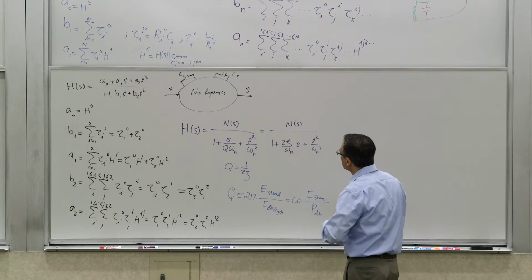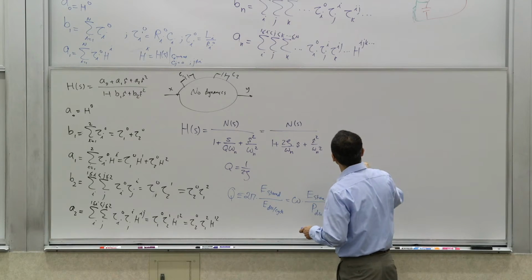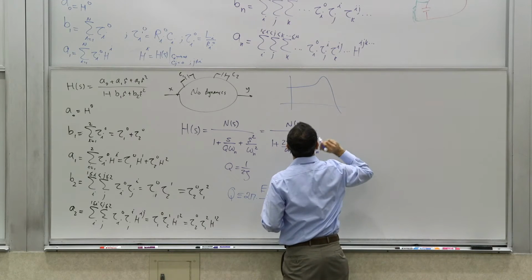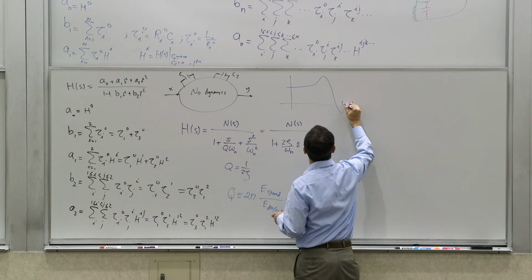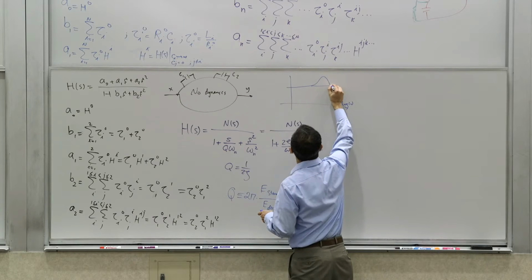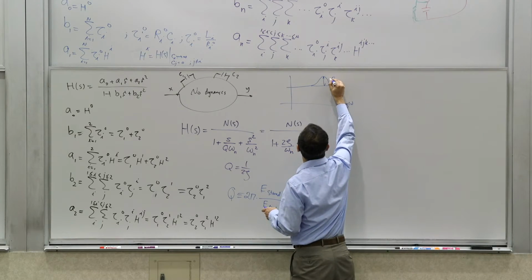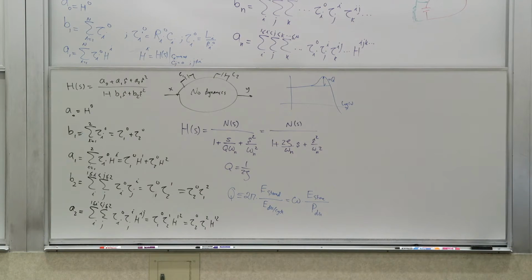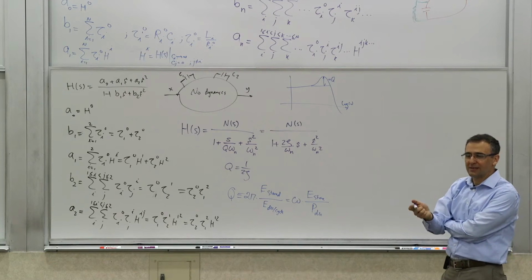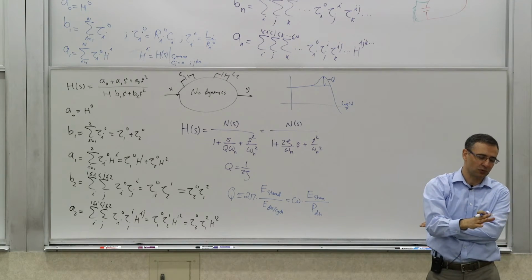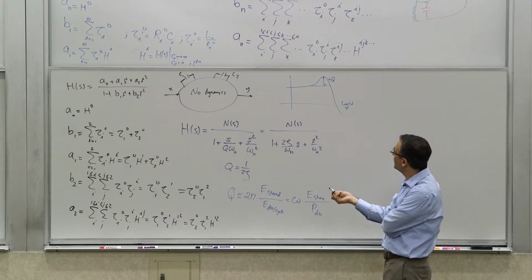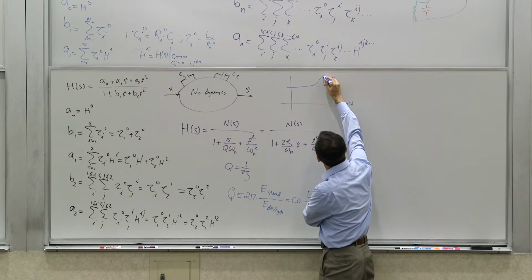And the transfer function of a low-pass system that has a high quality factor can look something like this versus log of omega, if you look at the Bode plot. And this peaking usually is around Q in absolute terms. Of course, in dB you have to calculate the 10 log of that, or if it's the magnitude amplitude, it has to be 20 log of Q in dBs, right? Now, what frequency does this happen at?